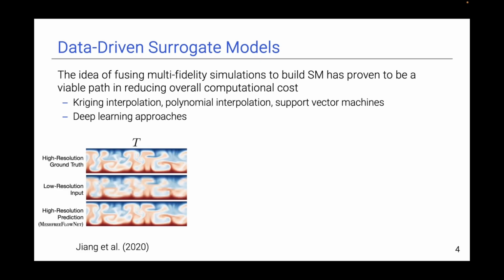So in this particular work, the authors were solving the Rayleigh-Bénard convection problem, where you have a cold plate at the top separated by some distance with the hot plate on the bottom, and then you have these buoyancy-driven effects that evolve the flow in time, sort of like the vertical features that you see there. So in their approach, they have a high resolution baseline ground truth from a high fidelity simulation on a really fine grid. Their model input is some coarser grid simulation with a relatively coarse discretization. And then the output of the model, again, aims to recreate this high fidelity prediction.